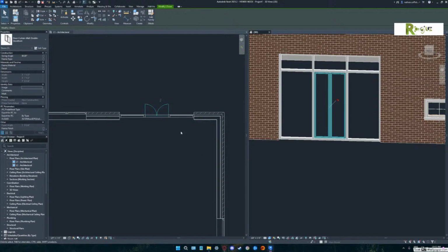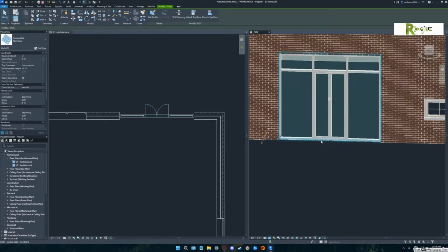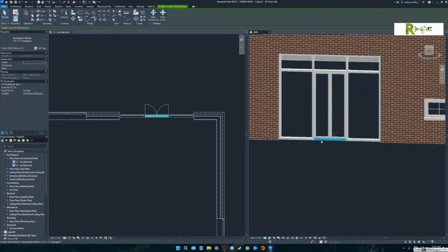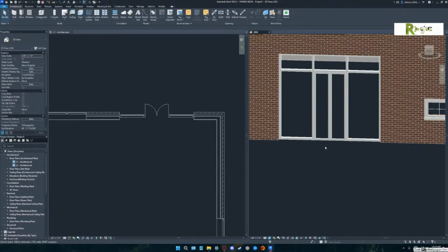Now, do you see at the bottom, there's a mullion going below the door? Can you select that bottom mullion? Yep, tab till you select it. There you go. Unpin it and hit delete. And you'll notice as you do this multiple times that tab goes in a certain order. It's going to first select the whole curtain wall, then it'll usually get the frame, then it'll get the panel.